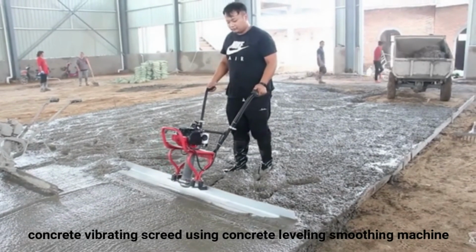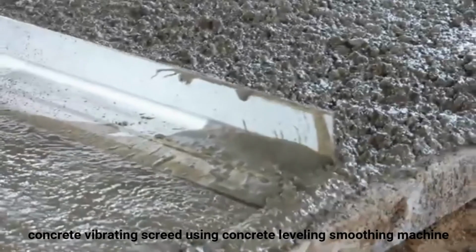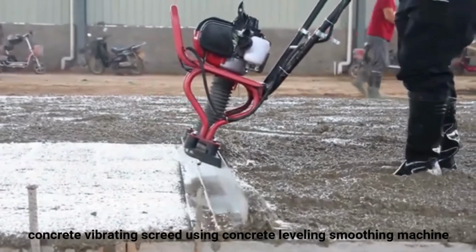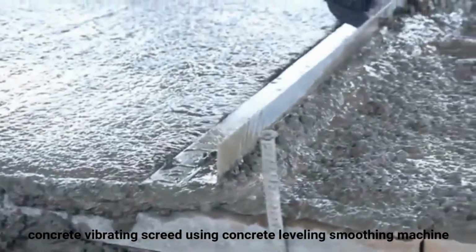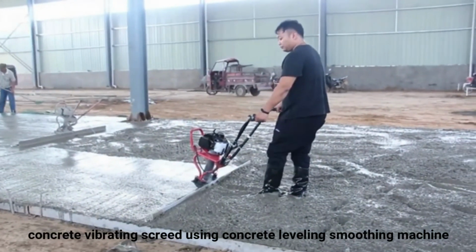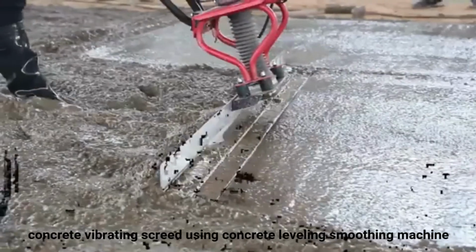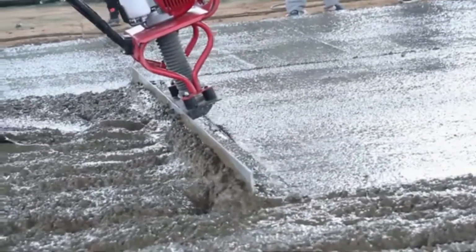Additional screeds must be set in between the form faces. These screeds are pieces of lumber or steel that are set parallel with one face of the form inside the area where the concrete is to be placed. The tops of all the screeds are at the same level. After the concrete in the slab has been placed and smoothed by this process, the concrete soon sets up. When the surface is stiff but not hard, the screeds inside the form are removed from the concrete, and the grooves they make are patched.